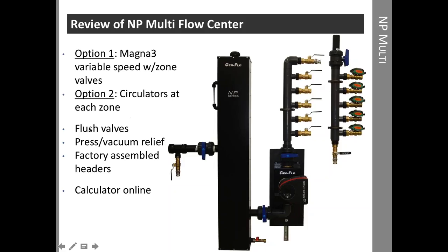All right, so this product is really a flow center. It does include flush valves, and typically we have insulated pumps and we have flow centers. Flow centers have all the parts and pieces, which is what this is. So we call this a flow center mainly because of the flush valves. The flush valves, you can see we have a cam fitting for the connection to your flush cart on the left-hand side. There's another cam at the return header, and there's a cam on the supply header.